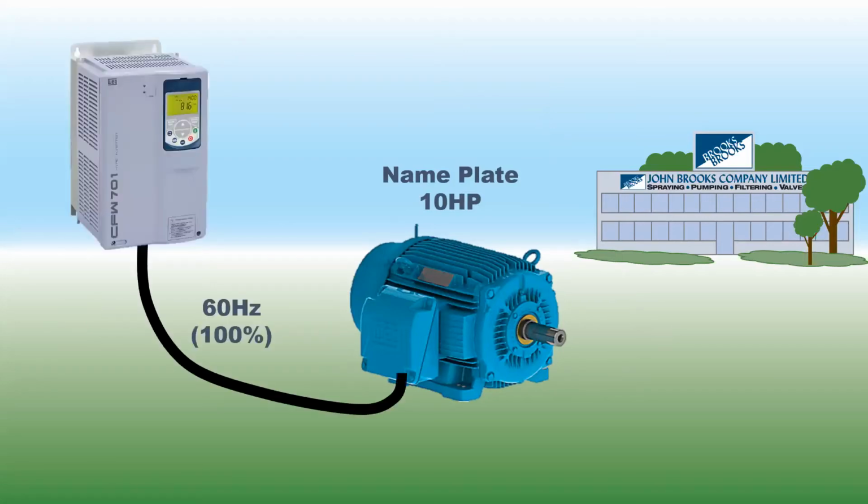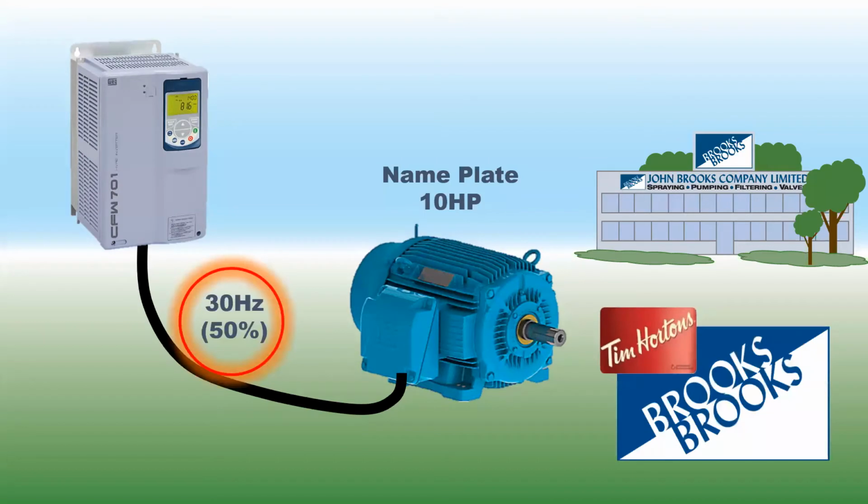Adrian? Yeah, so as Stefan said, when we're running at 100% speed or 60 hertz, we get the full nameplate horsepower from the motor, 10 horsepower in this case. If we're sizing this pump at a lower speed, lower than 60 hertz, we have to make sure that we derate it. So say that we're sizing the pump to run at 50% speed or 30 hertz. Can anybody guess what horsepower we're going to have available from the motor to turn that shaft? So we're halving the speed, okay.